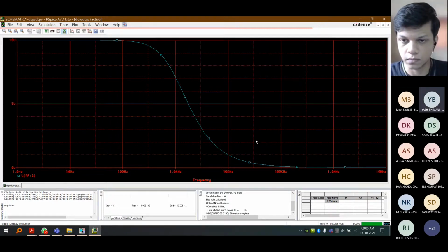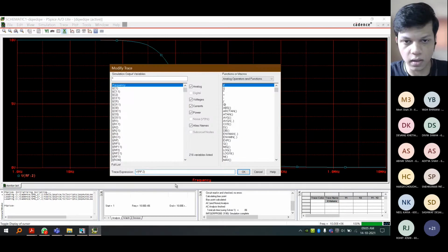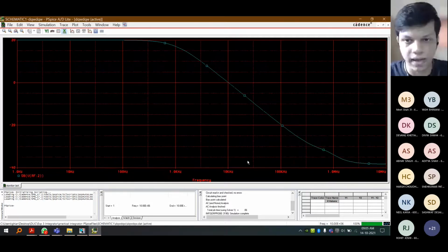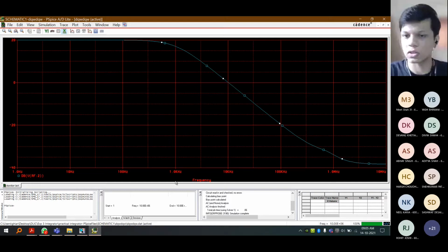Could you repeat the question? Yes, so in my integrator, I have not implemented any sort of formula for output voltage upon input voltage for my gain. But I still get the correct value of gain when I go, let's say I'm just going to type in dB here, into the decibel section. And you can see that I'm getting the correct value for gain at the points that I need. I'm getting 0 dB at 10 kilohertz. I'm getting 17 dB at 1 kilohertz. Why is that so without implementing any sort of formula? I should have to implement an output voltage by input voltage formula.